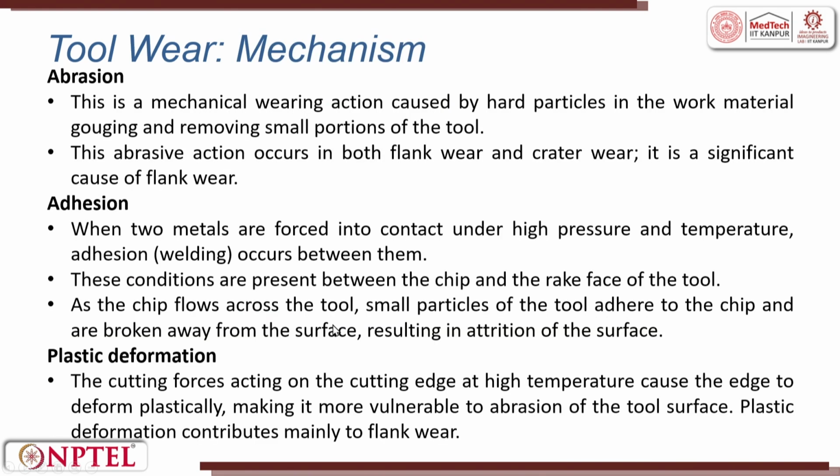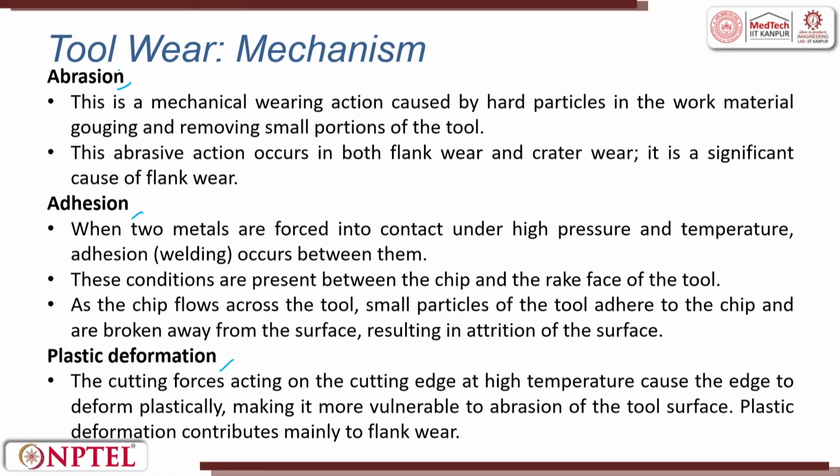The mechanisms generally can be abrasion, adhesion and plastic deformation. Abrasion is with hard particles, such as dissociated built-up edges, moving between the chip and the tool, where they create a scratch. This scratch, on acceleration, tries to chip off. So, that is abrasion.